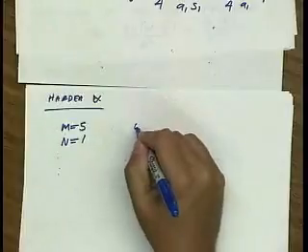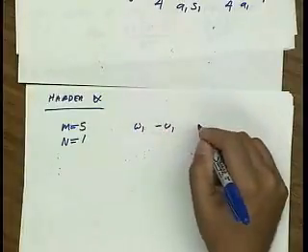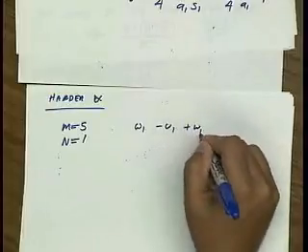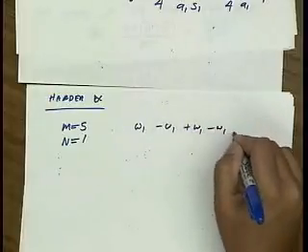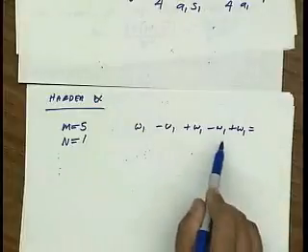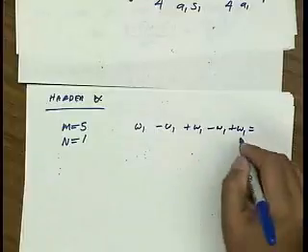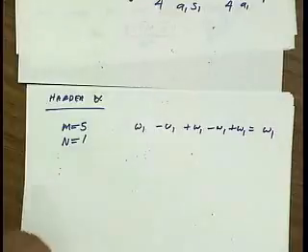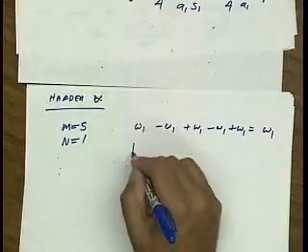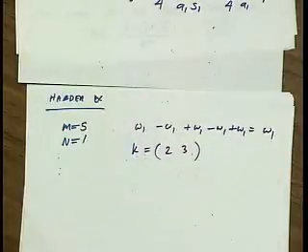And the observation here is that if I have basically 5 tones, then as long as I get a cancellation, so I have 3 omega 1s and 2 negative, I end up with a net omega 1. So any k vector like this will produce a tone at omega 1, right?